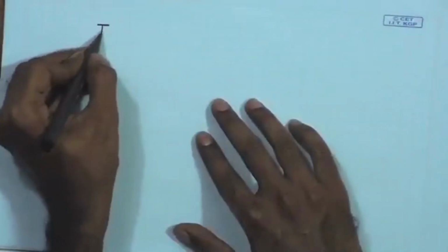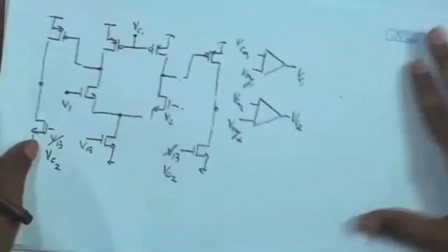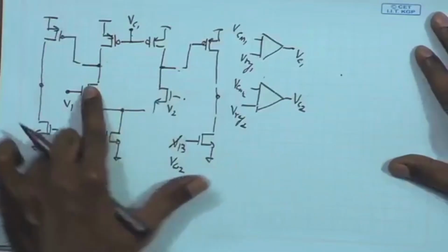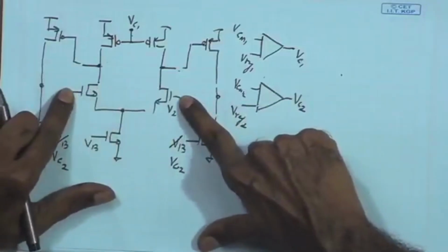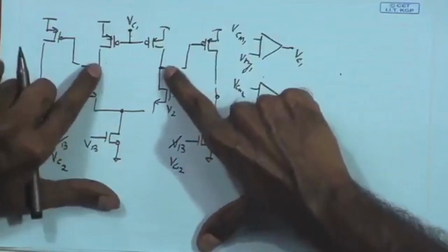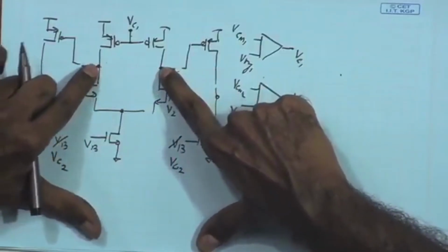So, we know that for a single differential amplifier stage, when we arrive at the common mode half circuit, we will be basically combining these two transistors together, combining the input devices together, assuming that the input voltage is the same, because if the input applied voltage is the same, the common mode value, the output DC point, will be exactly the same. As a result, we can tie them together.